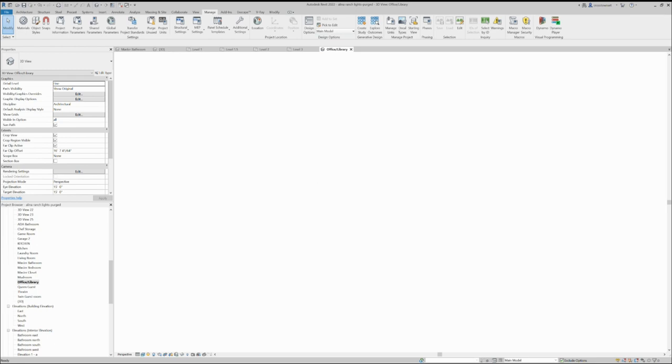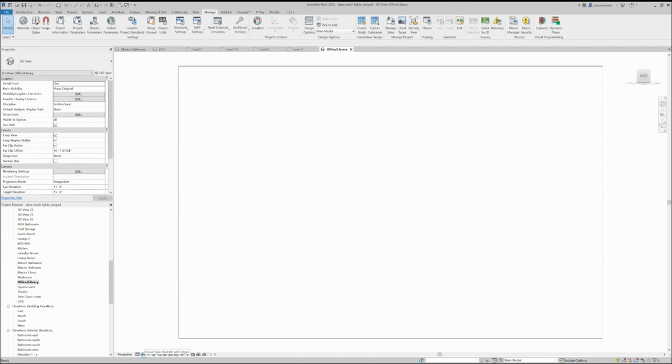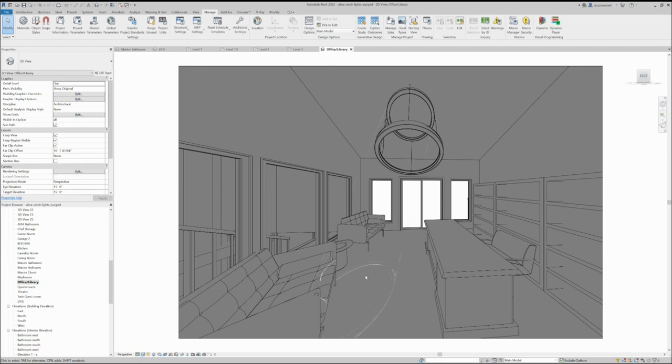I suspect that it's taking that time because this is set, this is a view control bar on the bottom left where it says perspective. You see that icon. I have to wait for this wheel to stop, but the visual style is set to realistic with edges. It takes forever to render. Got to change that to hidden line. Don't make life difficult for yourself here.